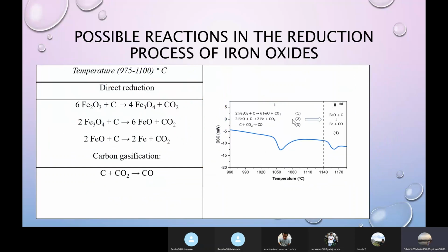The components of the raw mill scale before carbothermal reduction contain mainly wustite, together with magnetite and very little hematite. Therefore, during the carbothermal reduction process, the first endothermic peak in the DSC plot corresponds to the solid reduction of the oxides with carbon.